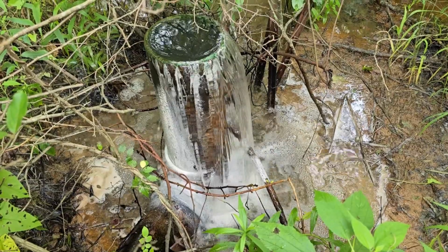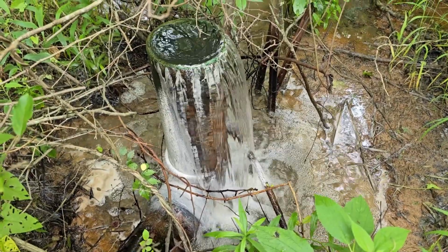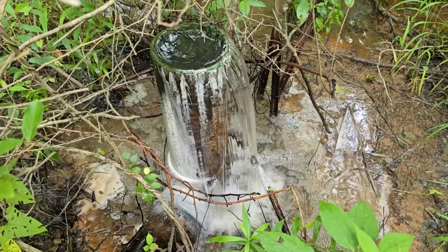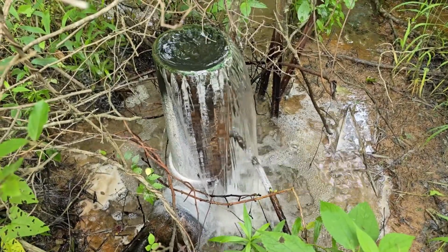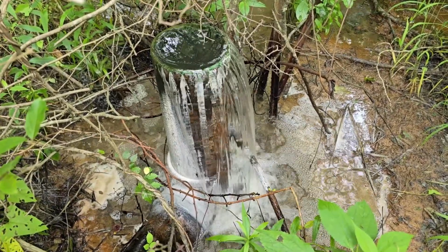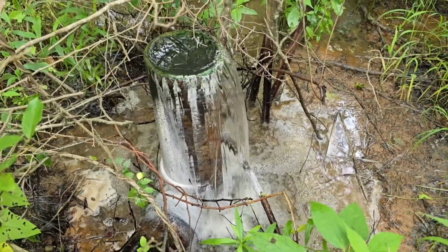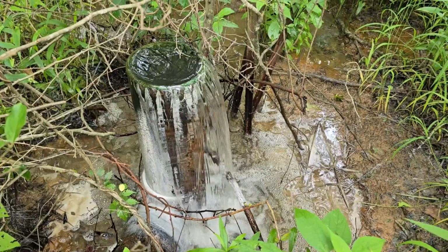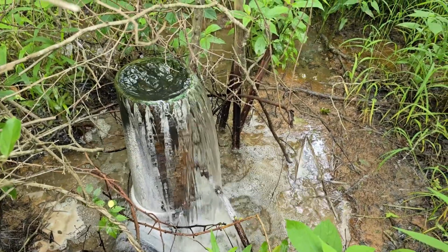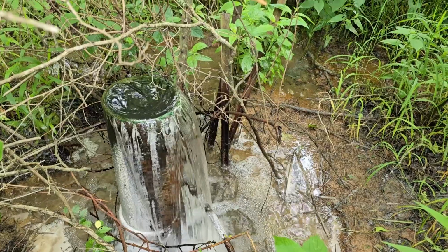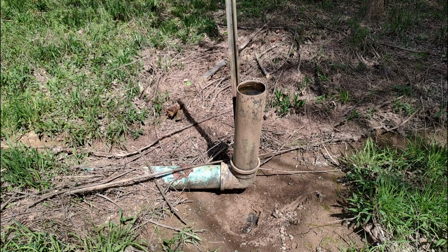At the outlet end of the drain pipe, we attached a 90-degree SDR 35 gasketed elbow and inserted a short section of pipe into the fitting. A laser level was used to set the elevation of the top of the vertical pipe so that it would be equal to the maximum water level that we wanted in the wetland. This upright pipe was attached to aluminum stake using plastic lock straps that later broke.